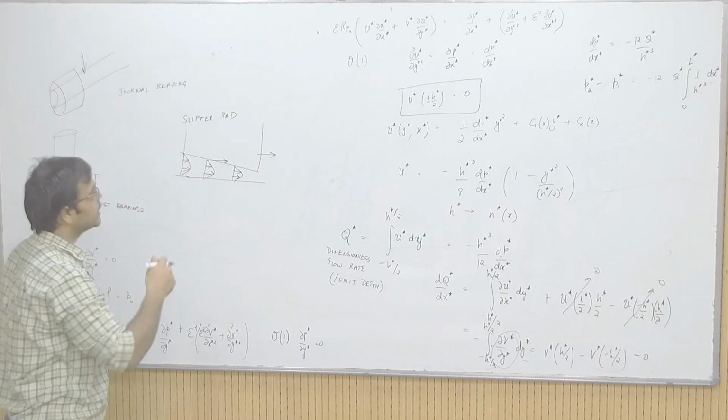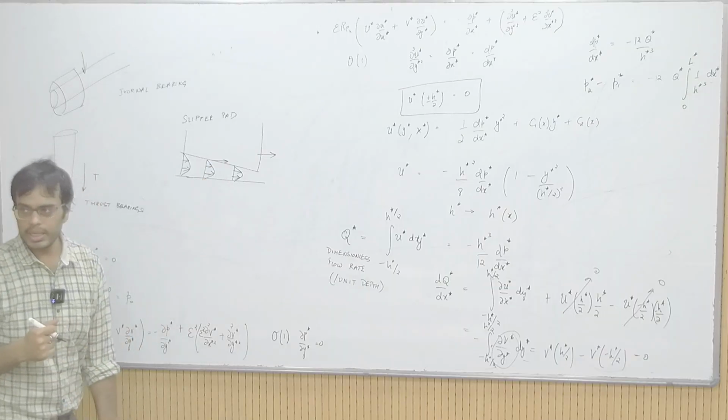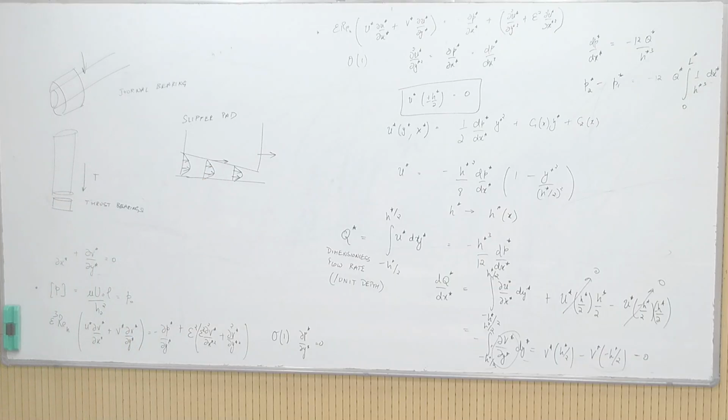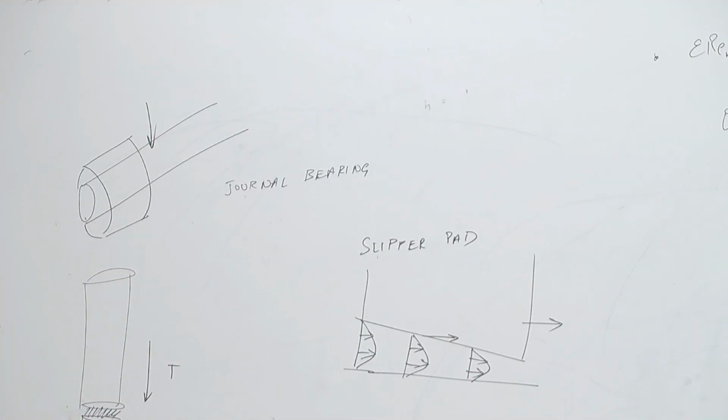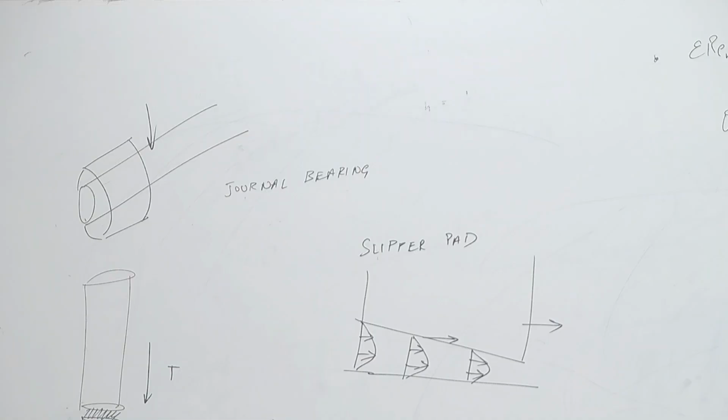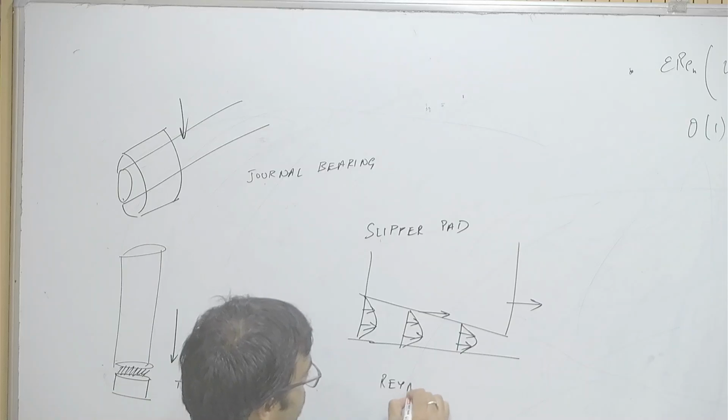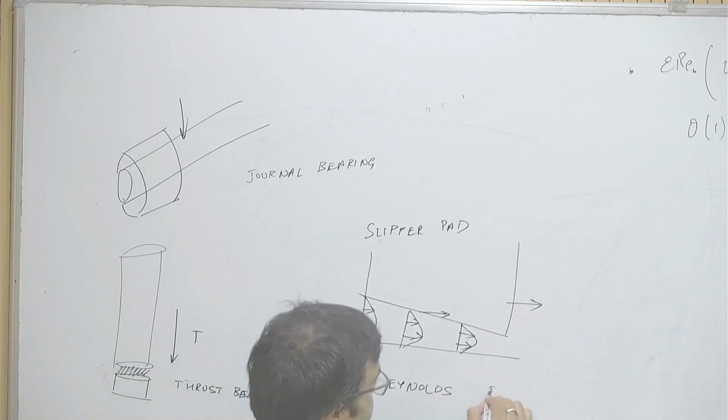In that case, the equation that you should be able to obtain is what is the thrust, or what is the pressure or the force, that this lubrication flow can sustain. Basically, you should be able to compute the pressure inside the flow and the viscous stresses due to the flow. Those can be computed by what is called the Reynolds equation, which we will derive now.